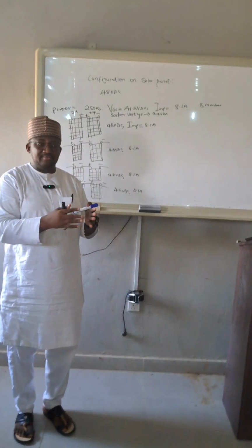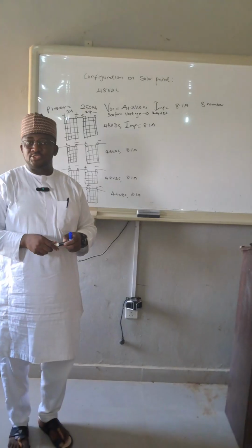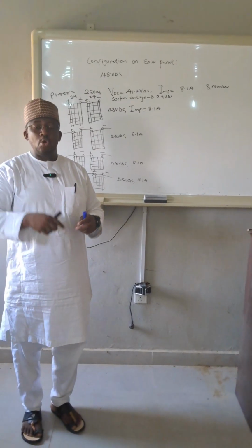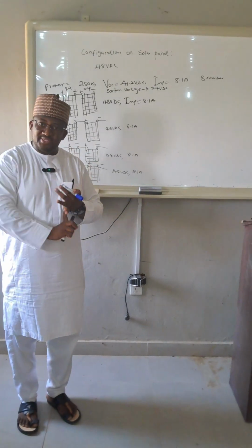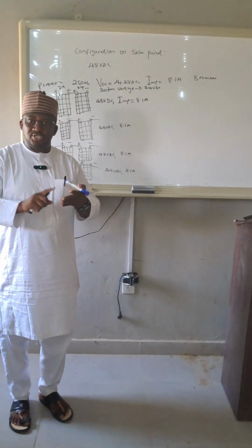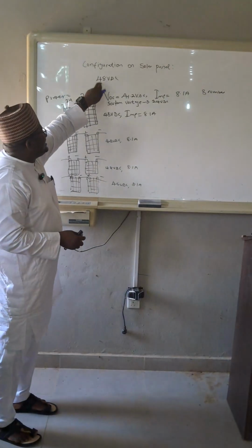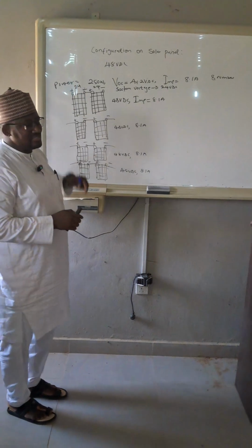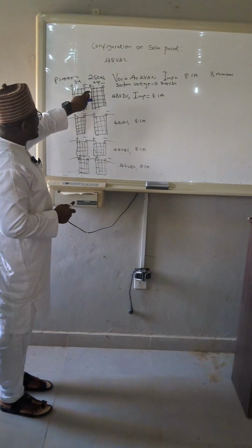If the inverter specification tells us that the system voltage is 24 volt, or 12 volt, or 36 volt, or 96 volt, we have to use that as the reference for all other components: battery, solar panel, charge controller, and the inverter itself. So now our inverter has indicated that the system voltage is 48 volt, which means we have to respect that directive.